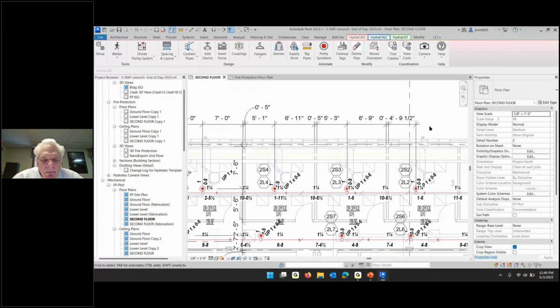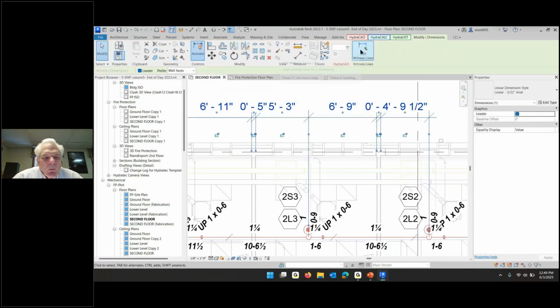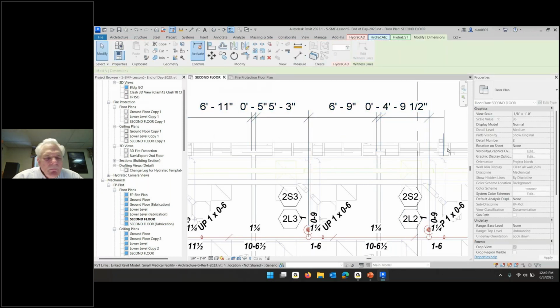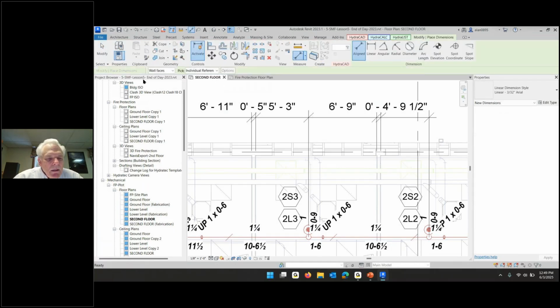And you were originally doing center to center walls, were you not? I switched to center and I switched back to face. As I'm dimensioning, edit witness line, I guess it was the dimensioning itself. In here it says dimension to center lines or faces.